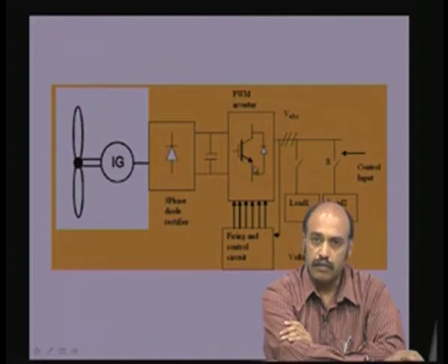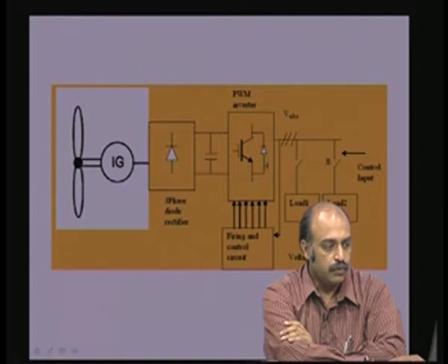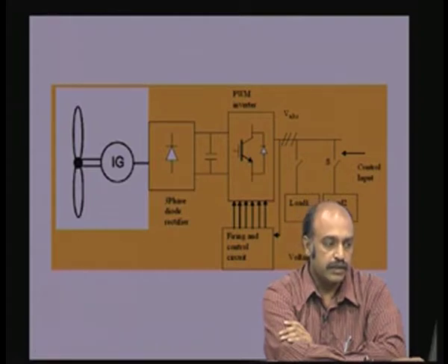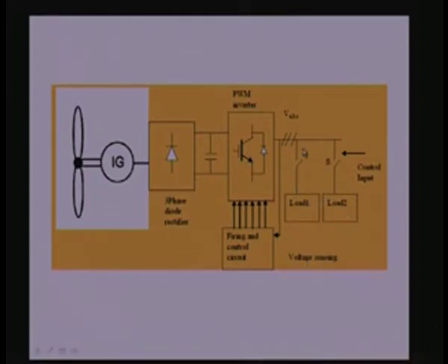by means of modulation. These are the modulation signals, firing angle. These are IGBT or MOSFET bridges. So, by pulse width modulation, you can get out here 3-phase or single phase sinusoidal output voltage, which can interface with the load or which can also interface with the mains, the grid. So, here again